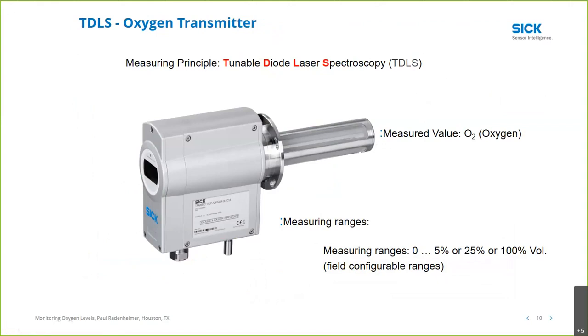What we're going to measure with this technology is the oxygen value in our storage tanks or in a flow line or a flare line. The measuring ranges can be 0 to 5, 25, or 100%. That is field configurable and is usually only set up one time when the application is being installed.